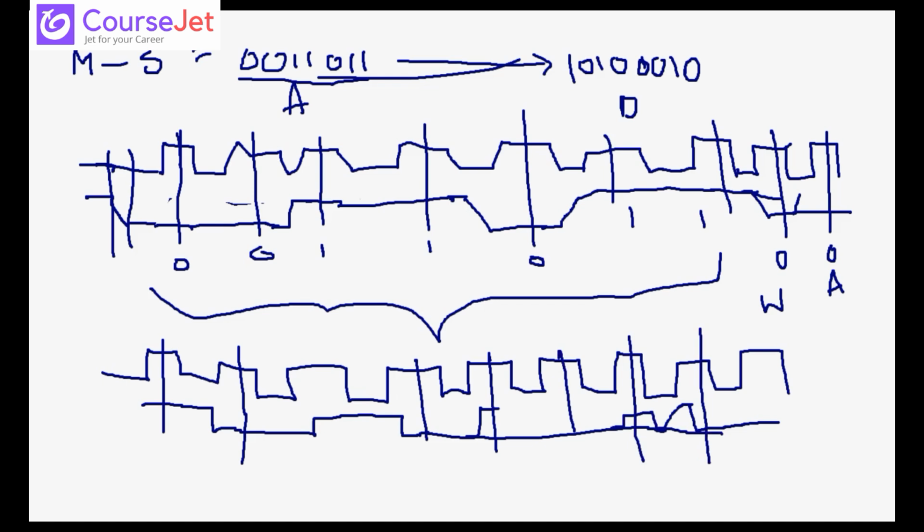Okay, and when you get an acknowledgement bit as 0, you will have to respond back with not of acknowledgement bit as 1. So here, if you are giving acknowledgement bit as 0, here you need to send a bit as 1, because the acknowledgement bit was 0.